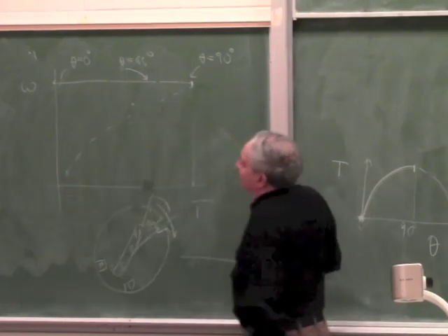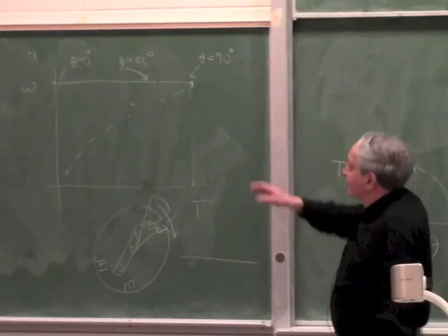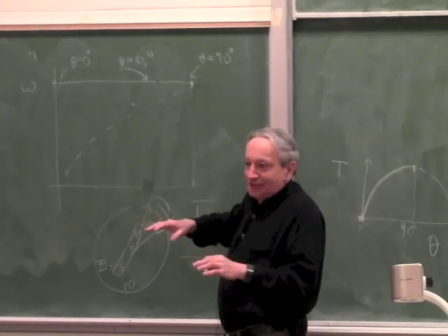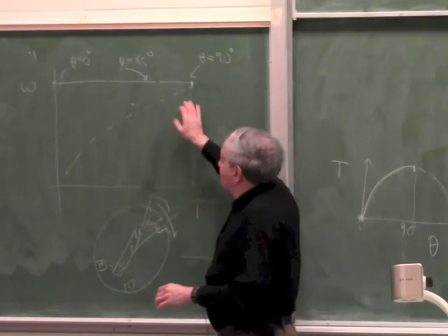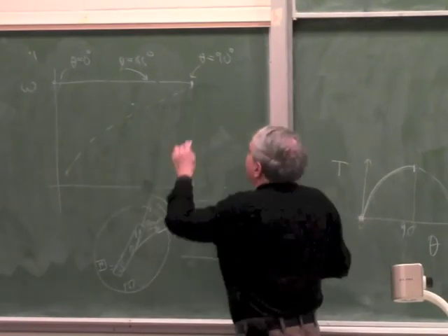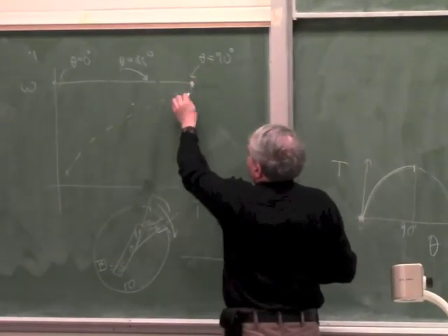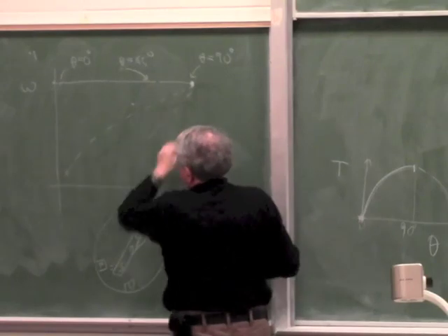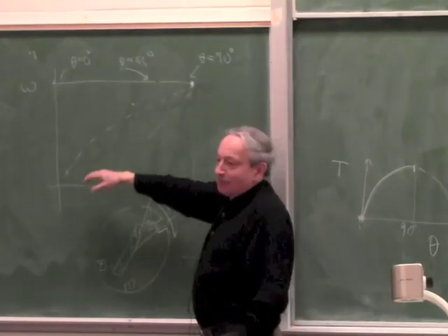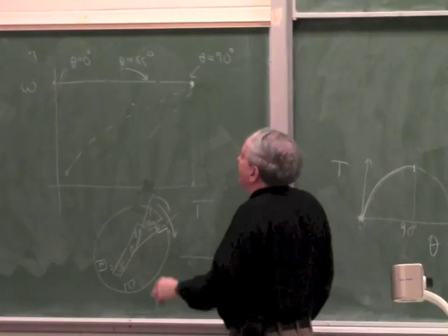It wants to go back to 0 torque and 0 speed. So there is really no graph here, because everything collapses. Right? You can't use this part of the graph, it collapses. So it really looks like this, and then who knows what happens. It either collapses this way or collapses this way, but that's not a stable part of the graph, it stalls.